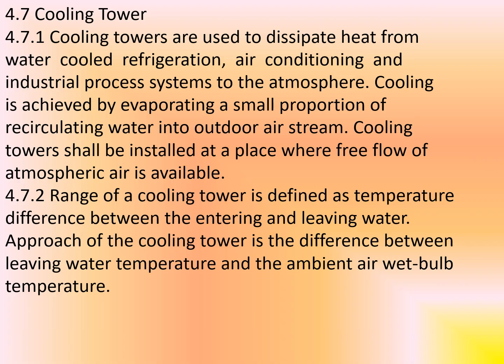Friends, cooling towers are used to dissipate heat from the water cooling refrigeration, air conditioning and industrial process systems to atmosphere. Cooling is achieved by evaporating a small portion of recirculating water into outdoor air stream. Cooling towers shall be installed at a place where free flow of atmospheric air is available. They can be either on ground or on top of the building.